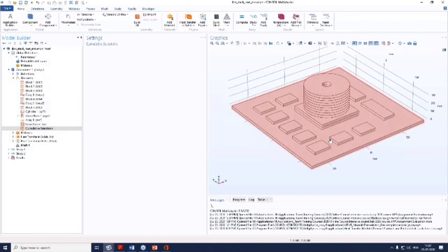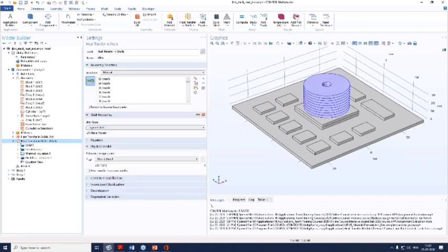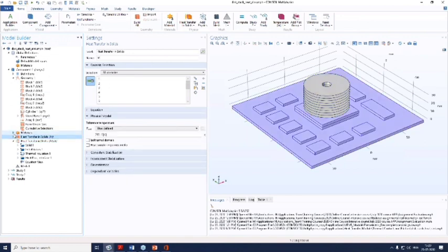They can be deleted. The selections you will not be able to delete are those being used anywhere in the materials, in physics or mesh. Once you start using those selections, you will not be able to delete them unless you remove them from there. So for any type of selection you need to ensure that they are not getting used.